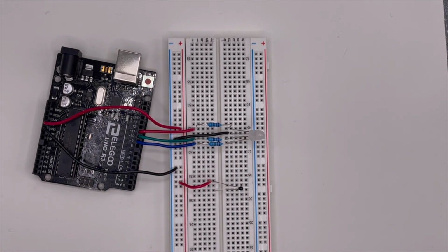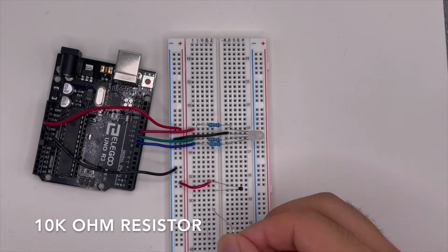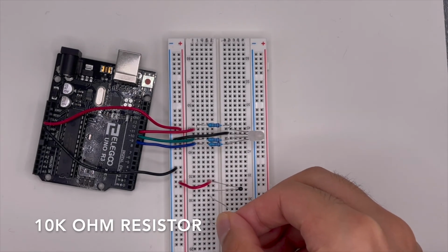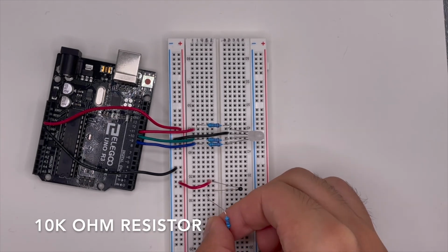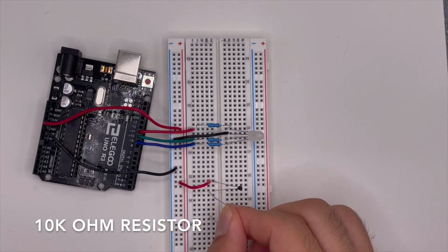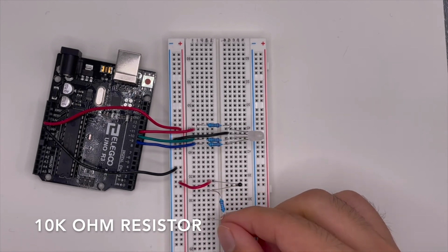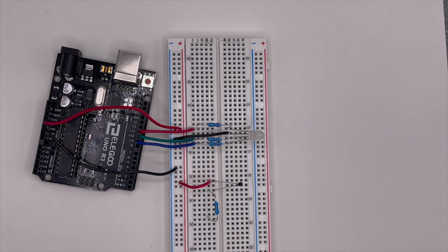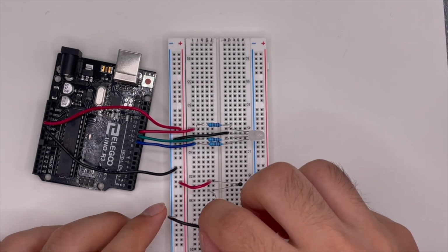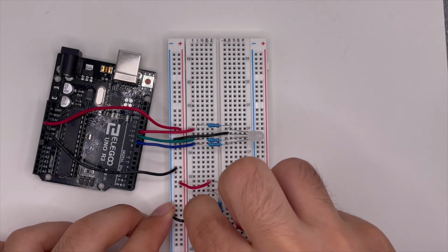Before we connect it back to ground, we will also be putting a resistor in between so we can have current flow through it. Make sure to put the two legs of the resistor, one in a separate lane and the other in the same lane, sharing with the temperature sensor. After that, we can connect our ground pin from the resistor there to the negative bus lane.